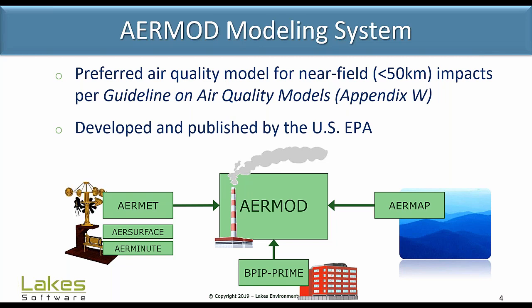And as you can see from the image there on the screen, AERMOD itself is the air dispersion model, where you input the sources, their emissions, the receptors where you would like to calculate concentrations or deposition fluxes, and it performs the dispersion calculations of whatever pollutant it is you have of interest. But it's also made up of a number of different components, such as AERMET, which itself has preprocessors, AERSURFACE and AERMET. And in AERMET, you input raw meteorological data and you get out formatted meteorological data files for use within the AERMOD dispersion model.